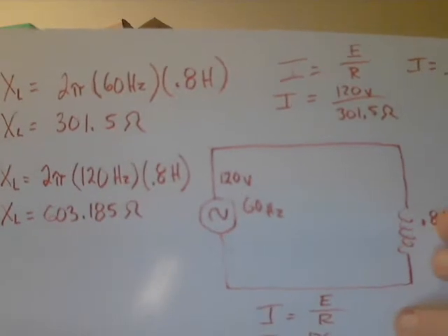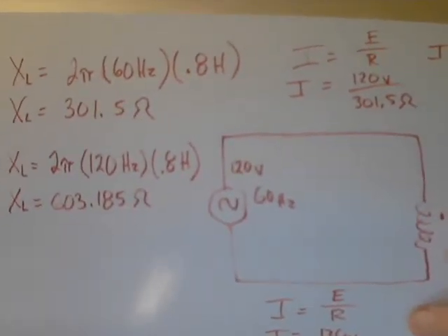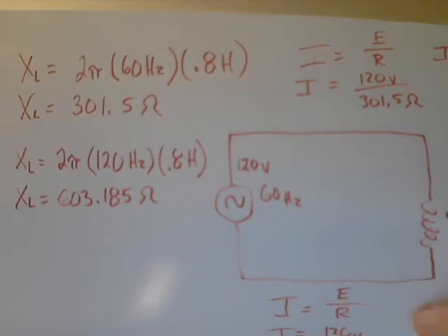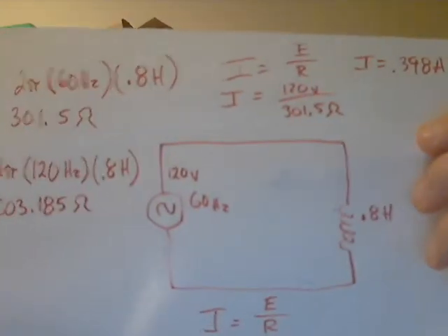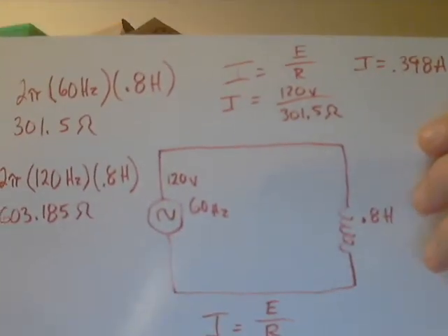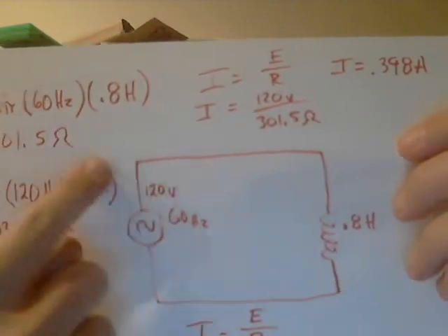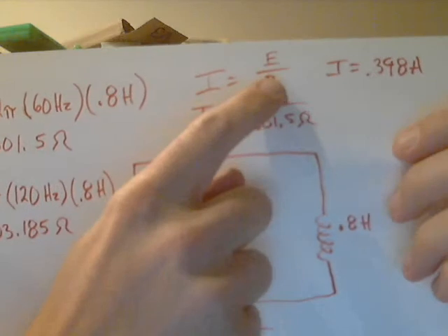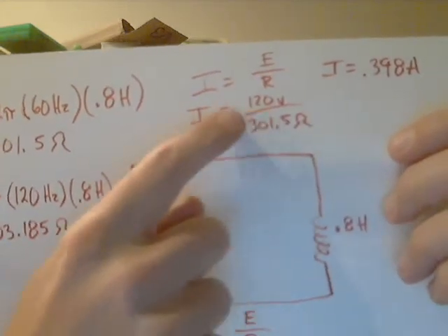We certainly don't want 12,000 amps flowing, which could have happened if we had a really low resistance in the wire and then we just decided to plug it in without any loads or resistors. Notice here in a purely inductive circuit, where there are no resistors, I can actually use Ohm's law and substitute the R with X sub L, or inductive reactance, to solve for my current.